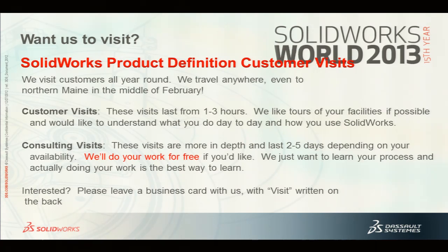No, because a plane is really only defined by 3 points. Are you talking about a reference plane, or a planar surface extraction? Yeah, you can pick any of those tools you want. How successful they're going to be is the question. So if you have what you think is a planar surface and you pick 3 or 4 points on it, you're really not picking points, you're just picking the decomposed part of that mesh. If you identify that and you go to one of those tools like plane and you pick it and it looks like the right solution, bonus. If it doesn't, then you've got to go to the other ones, like maybe it's a toroidal or a ruled surface. Remember I talked about interpretation? You get involved in the interpretation. You help SolidWorks understand what those individual decomposed surface meshes are.